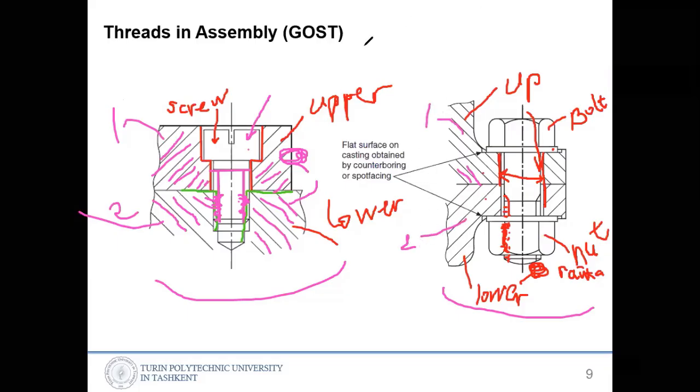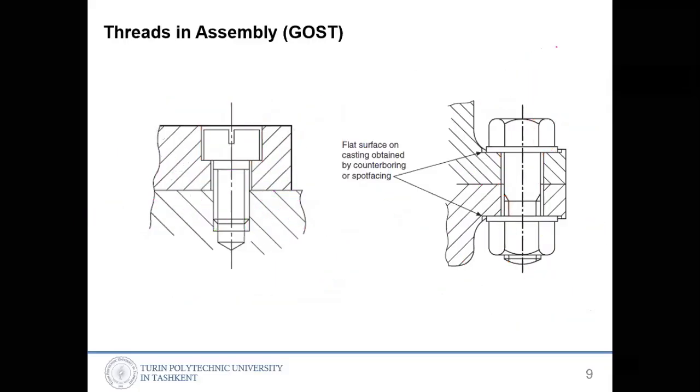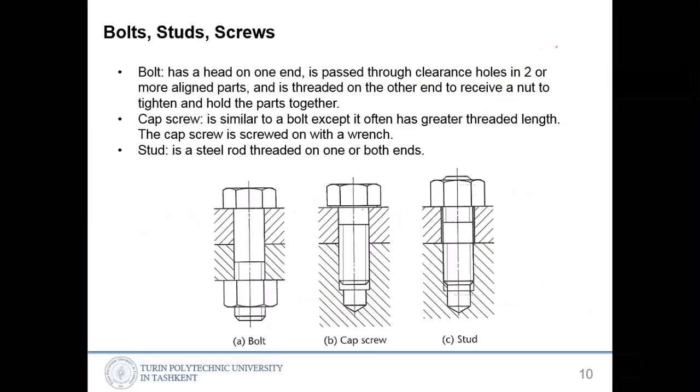And there's also a rule: screws, bolts, nuts, and any joint of this kind of temporary joint are not sectioned. Here, even though the front upper part and lower part are sectioned, the screws and bolts are not sectioned. That's a rule, because those are common parts, so they are not sectioned. And yeah, what's next? The main difference, there are also studs possible here.